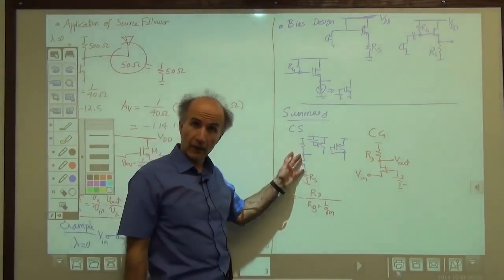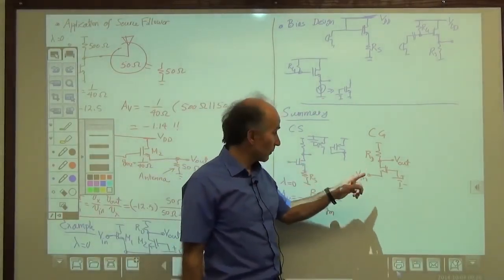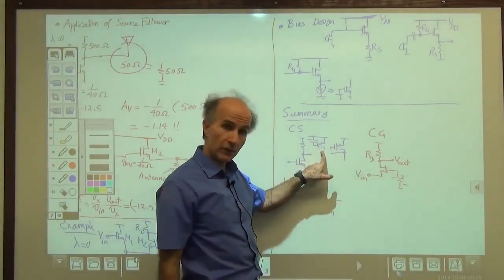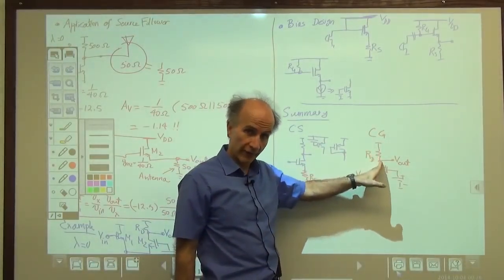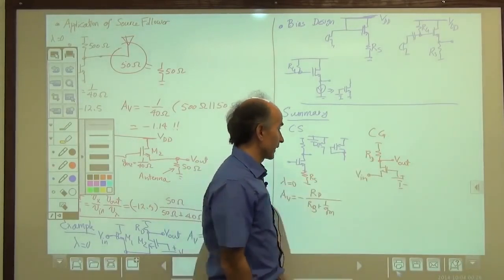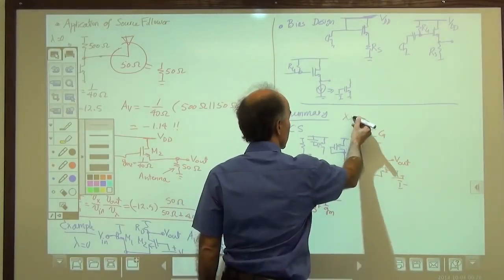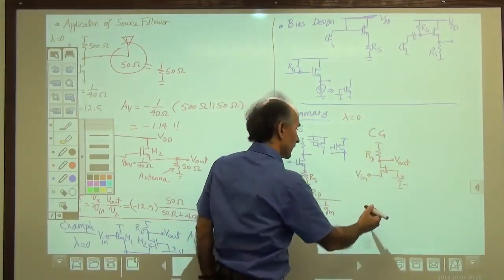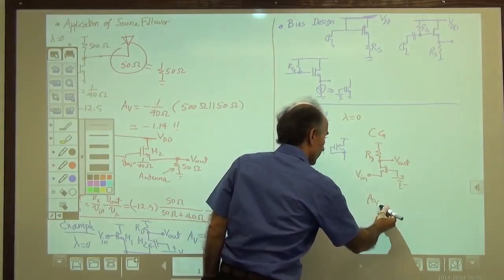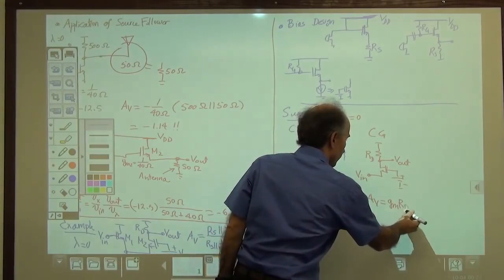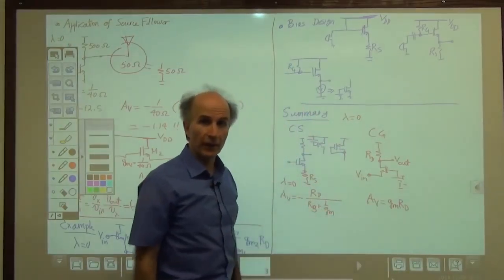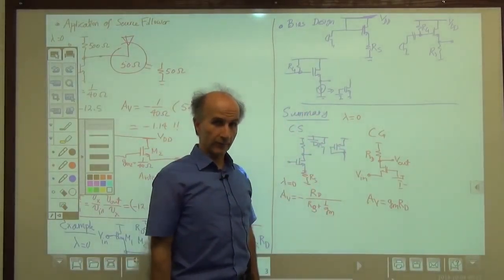Again, like the common source stage, we can replace this load with a current source or a diode-connected device. So it doesn't have to be a physical resistor. And we saw that again with lambda equals 0, so let's just say lambda equals 0 for now, the voltage gain of the circuit was given by GM times the total resistance tied between the drain and AC ground.